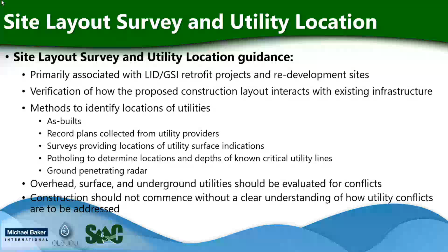Overhead, surface, and underground utilities should be evaluated for conflicts with different phases of construction. And construction should not commence without a clear understanding of how utility conflicts are to be addressed.